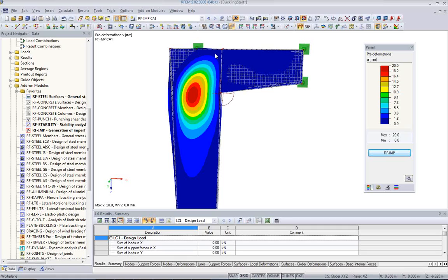Actually, if you use the Eurocode 3, also EN 1993-1-5, you find here some hints how big those buckles have to be. And if you use a plastic design, it should be 1/100 of the reference length. And the reference length is the distance of the edge of the buckle, I would say.